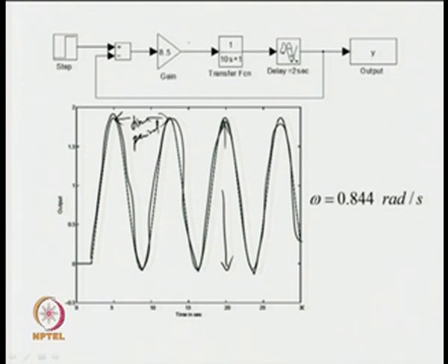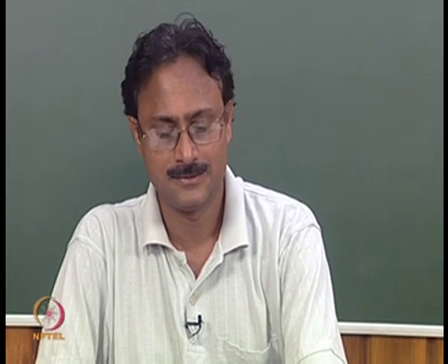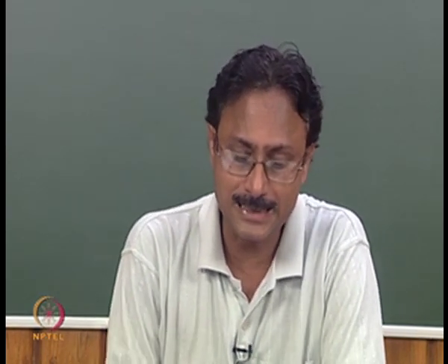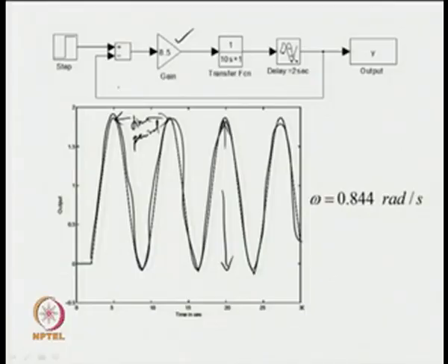When the proportional gain becomes more than 8.5, what happens to the closed loop system? We may get unstable output from the closed loop system. So, there is some risk. So, one has to go on trying various values for the proportional controller.